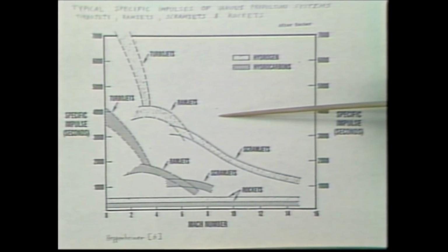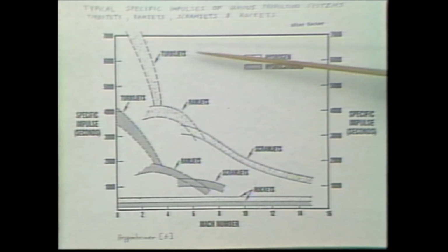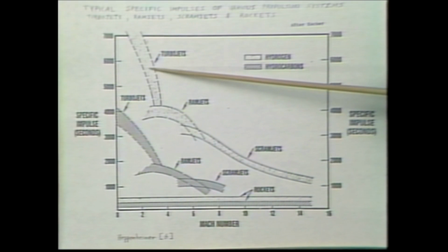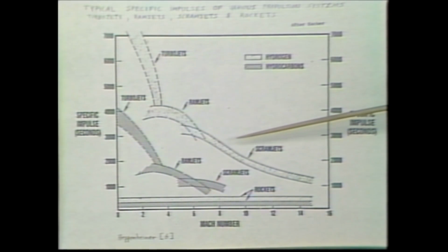Okay, we'll start in with selecting propulsion systems. Dr. Lewis already showed this same basic plot showing the specific impulse, or performance, of the engine with Mach number. Turbojets are clear winners at low speeds, and then ramjets and scramjets at high speeds, all of which are better than rockets. You'll see later why specific impulse is important and how it factors into aircraft size. I derive that a little bit later. It's wrapped up in the rocket equation.